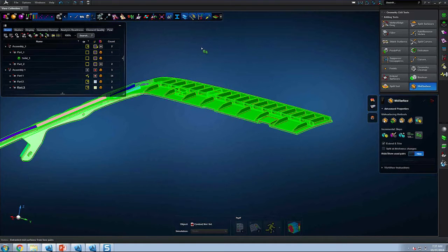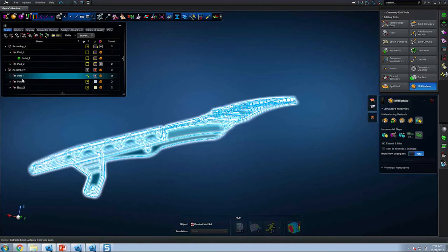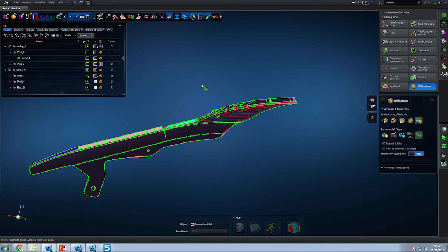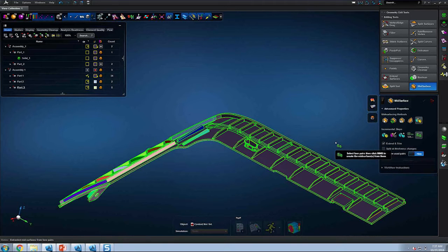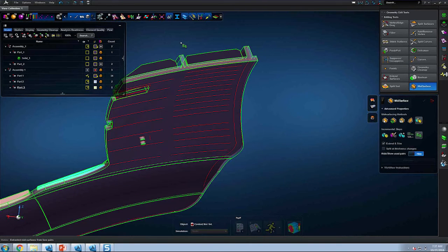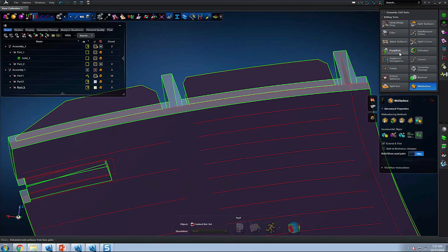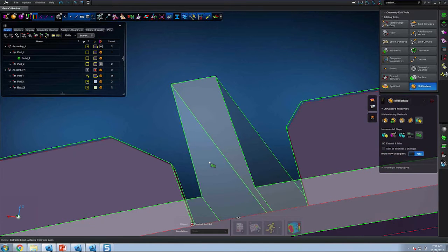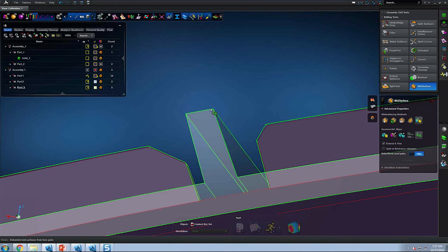Right now, what I've gone ahead and done is I've performed midsurface extraction of another piece of the model. I like to do this in an incremental fashion. It helps me reveal any issues that might be relevant or apparent in the extraction method. Here, for example, we've created a nice piece of geometry at the midplane of this drafted angle rib. But here we didn't extract the geometry. So that's something I have to go ahead and fix in a moment.